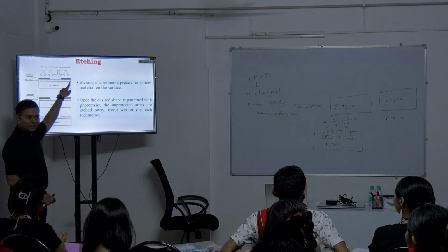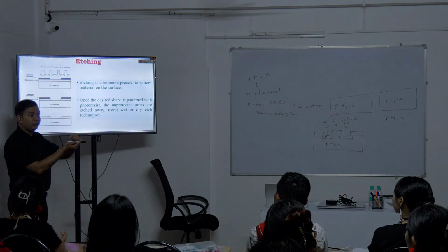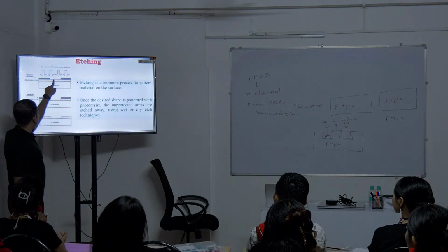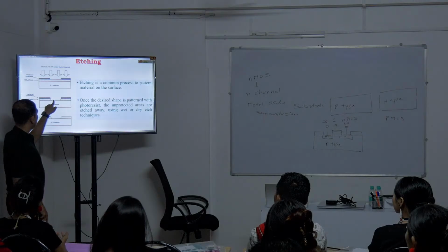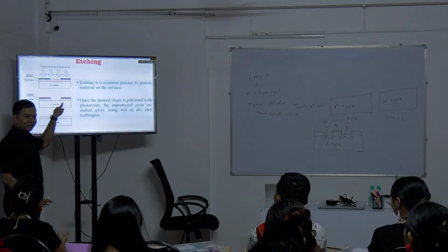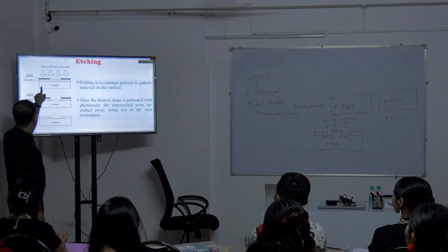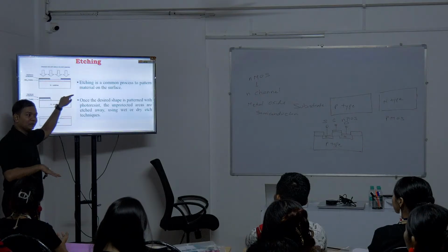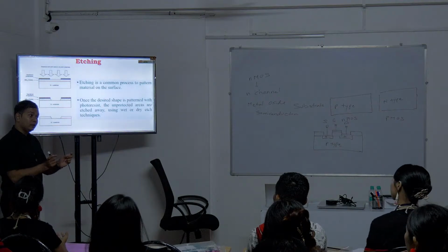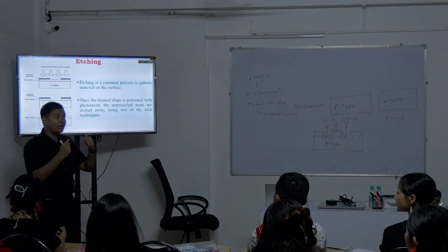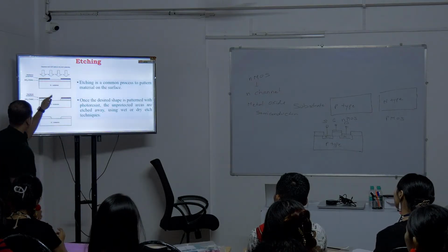Hope you're understanding. I'm covering it with that portion, so when I put some chemical, that portion will not be affected. But because this portion was not covered by any mask, when I put it under the chemical, it can easily be removed from this portion. So I'm basically trying to save these layers by using this particular photoresist mask. Understand? The photoresist mask is going to prevent the oxide layer from reacting with the chemical that we are going to use.